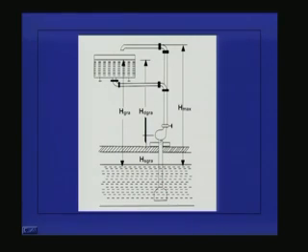Let us say this is the pump here, this is the sump, this is the water level in the sump, this is the water level in the delivery reservoir. Now, at the water level in the sump the pressure is atmospheric, whereas on the suction side of the pump the pressure will be below atmospheric. That is because as the water goes from this level to this level, there is a change in the head. So, correspondingly the pressure decreases, and there is also the head loss in this suction pipe. Because of that, on the suction side you always have negative pressures.